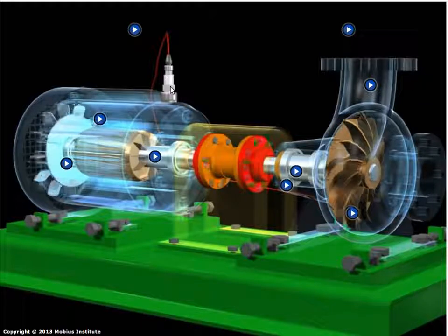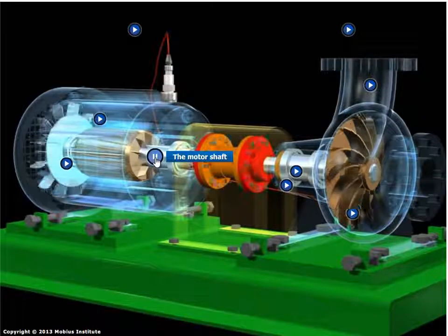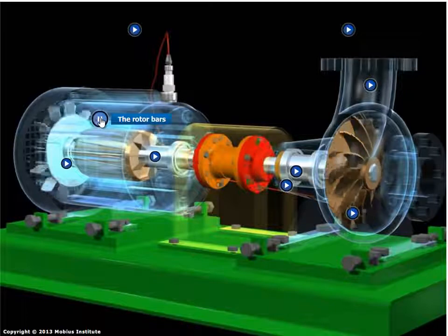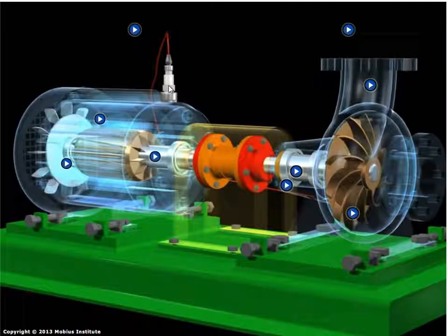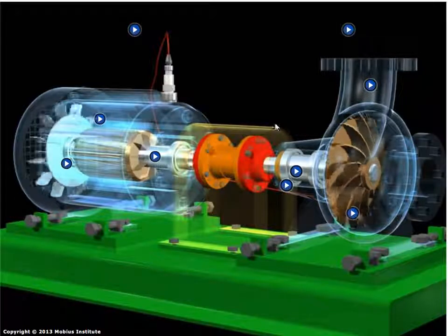But one of the keys is that vibration analysis, in a sense, enables us to sort of listen. Well, what is happening with the shaft? What's happening with the bearings? What's happening with the rotor bars? Now, we pick up all those sounds from here. They all combine together into one measurement, but separating them in frequency and some of the other things we'll explain let us do that, so we get an idea of the health of each of those components.